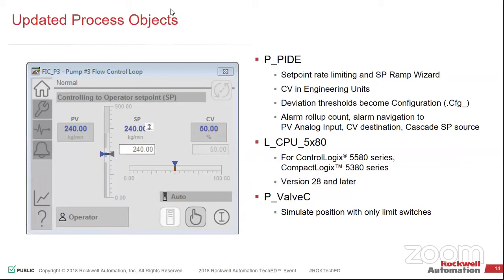So one of the things I came up with is, when you launch an L8, the LCPU option, that is a block that tells you all of the information. The task monitor tool, if you've ever used that, that information was part of that LCPU. It was a little add-in graphic so that on the HMI, you would be able to see the memory usage, the CPU usage, the connections that you have on a processor.